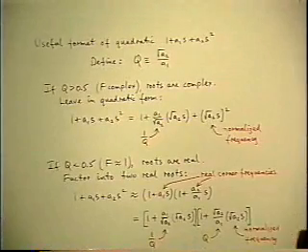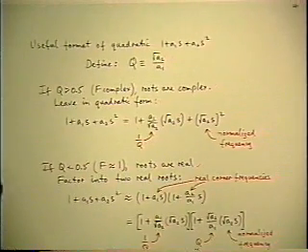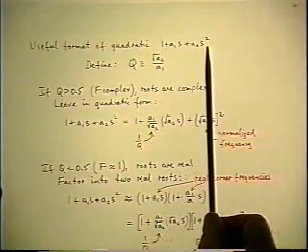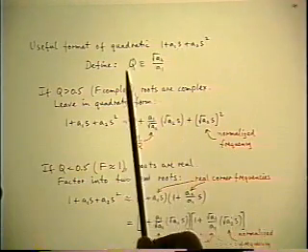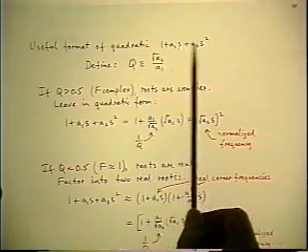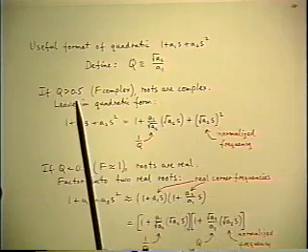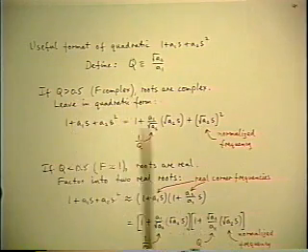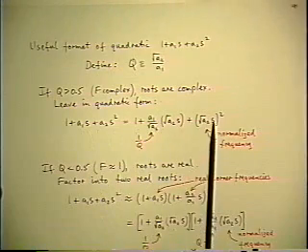So here's the way to approach finding out which case is relevant in your particular problem. Whenever you find a quadratic, the first thing to do is to find the value of its Q factor, which you can do directly in terms of the known coefficients. If Q is bigger than 0.5, you know you have a complex pair, and you should leave the result in the quadratic format,